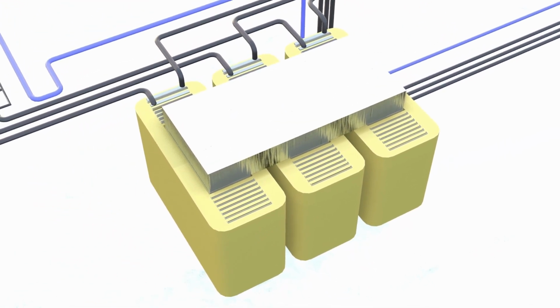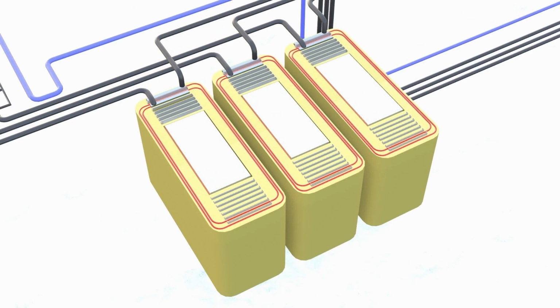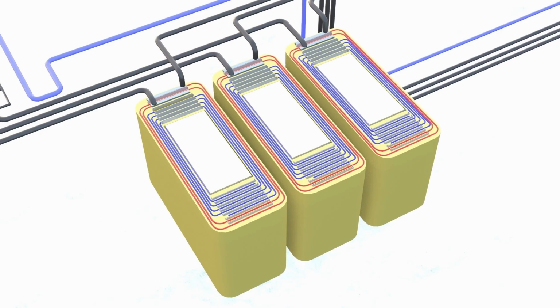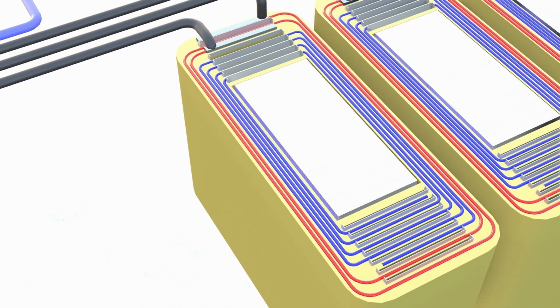In addition to the primary winding just described, a secondary winding is applied directly to the core, which is shown in blue color. This one is also equipped with additional air gaps. Setup same as main winding. The secondary winding, electrically speaking, is still galvanically separated from the primary winding, but already magnetically coupled to the primary winding through the core.